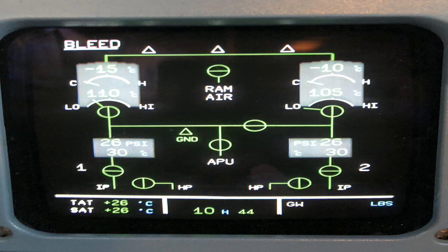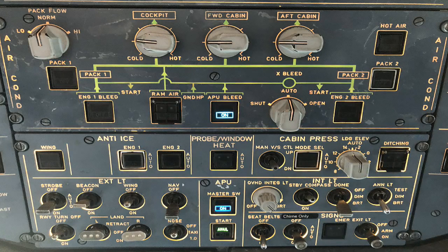Well, I'll get into the components in a little bit, but I'm just describing that there are two push buttons on the panel, engine 1 and engine 2 bleed, and a fault light that could come on when there's a fault. If there's a pylon or wing overheat detection on either the right or left side, that fault light is going to come on in amber. If the engine 1 and 2 PRV is not automatically fully closed during engine starts, then that fault light is going to be on. And remember, over temperature downstream of the precooler will also show up in amber.